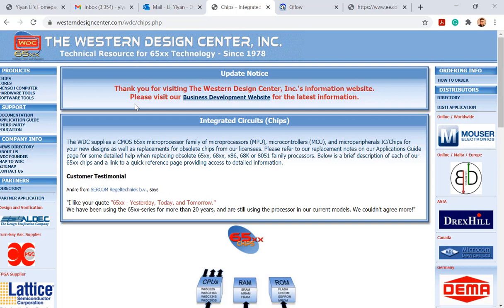But if it's ASIC, it's totally customized. They can fabricate all the chips, all the wires and transistors based on the GDSII file in the foundry. The cost will be higher if you only fabricate 20. For 350 nanometer technology, I think it's going to be over $50,000 just for a prototype of 10 or 20 chips.